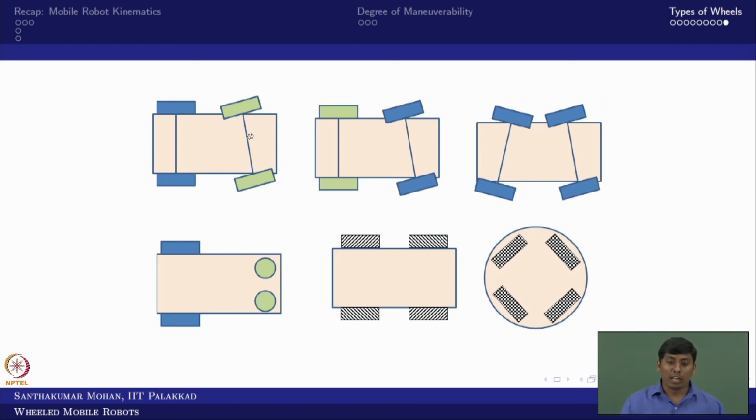You can see this is a kind of tempo, where the rear wheel is powered and the front wheel is steerable. In the sense, 2 wheels attached with a single axle, but that is steerable, and the rear wheel is attached with a single axle, but that is powered. For example, a truck, or a van or tempo and all. So you can see the number of controllable inputs is 1 with the locomotion, which provides the traction, the other one is steering, in the sense 2. And this is a car where the steering and the front wheel are powered.